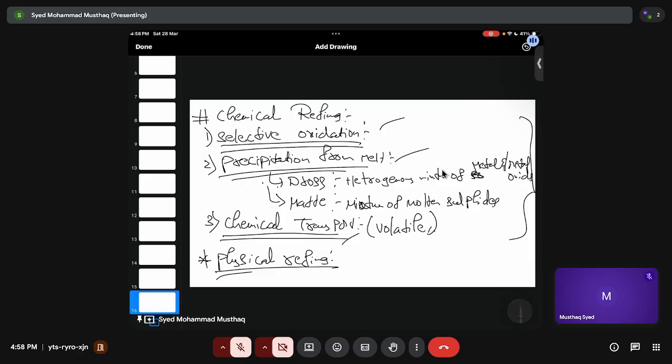The sulfur is removed by oxygen, where we purge oxygen. Oxygen will react with sulfur, give sulfur oxide, and some of the impurities also will get oxidized. So like aluminium, silicon, manganese, zinc, tin, many elements will get oxidized, and they will be picked up by slag. And some of the copper will also get oxidized, but again we maintain some reducing atmospheres. We do the deoxidation to get rid of copper oxide, okay.